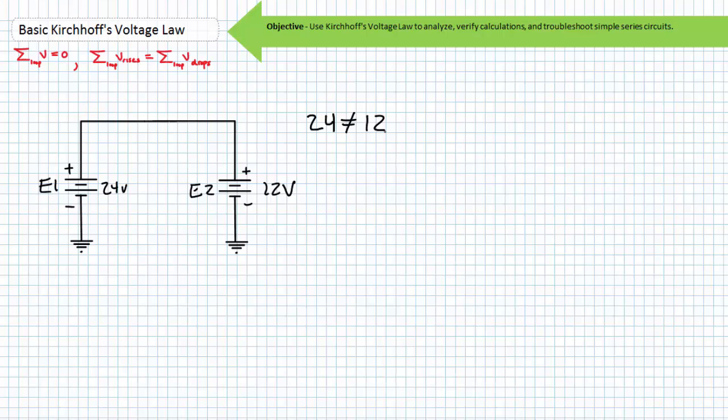What is missing in our schematic is the real-world resistance of the wires forming the connection between the sources. Ordinarily, this resistance is beneath our level of concern and is purposely ignored. In this case, however, this tiny resistance is the only opposition to this differential, in this case 12 volts. I'll redraw the diagram to include the resistance of the conductors between the 2 sources and use this tiny resistance value and resultant current draw to illustrate how incredibly dangerous this configuration is. Let's say our wire is now modeled as a resistor with a magnitude of 100 milliohms or 0.1 ohms.